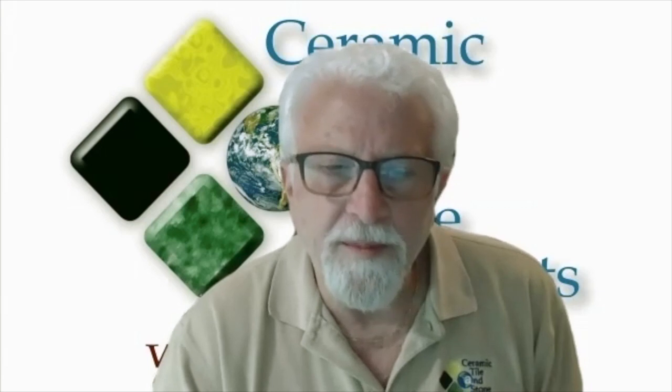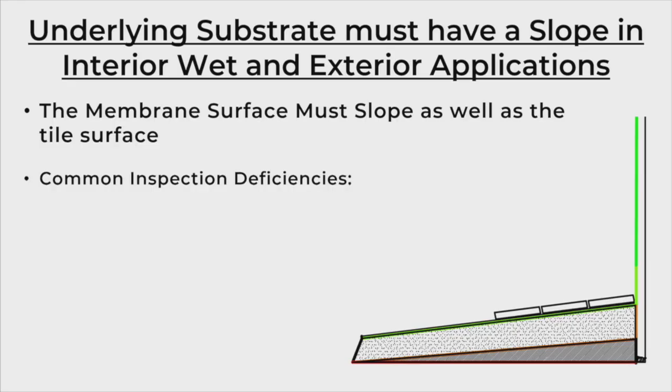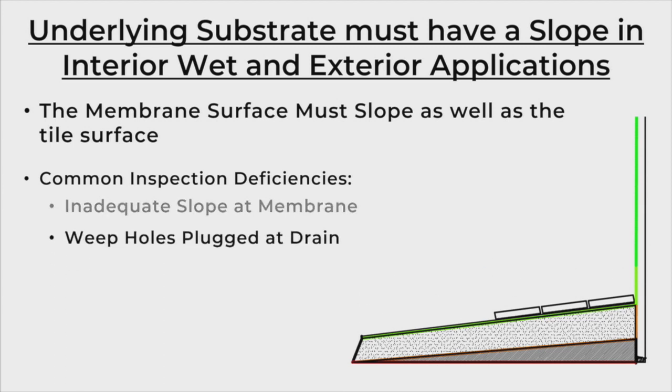In addition to that, we always recommend putting the membrane on top of the mortar bed and bonding the tile to it, because that keeps the moisture out of the mortar bed, which can retain a lot of moisture that can lead to problems. So the common deficiencies that we find during our investigations: inadequate slope at the membrane, and I'll be showing you a case study where that has occurred.